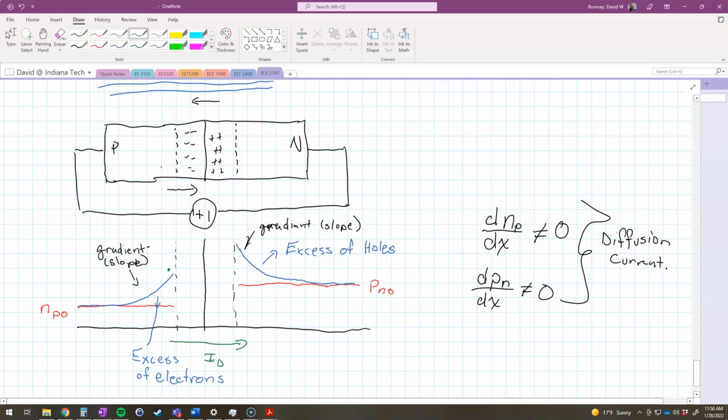And we know this particle, whatever charge it is, in this case it would be positive because it's going to the right, but there's current moving, so this thing's moving and it will enter the depletion region. But then you might say, well, wait, you can't have any free carriers in the depletion region. And you're right, we don't really have free carriers. But what happens is it just gets swept clear across the depletion region and gets put over to this side and then just continues its journey on, setting up this current that we call ID.